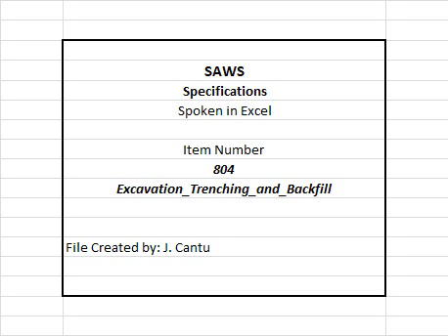extended. 2. Excavation. A. The contractor shall perform all excavation of every description and of all substances, including rock, encountered to the lines and grades shown in the contract documents or as determined by the engineer. During excavation, material suitable for backfilling shall be stockpiled in an orderly manner a safe distance from the banks of the trench to avoid overloading and to prevent slides or cave-ins as per 29 CFR Part 1926 Subpart P, entitled Excavation, of OSHA Safety and Health Regulations for Construction.